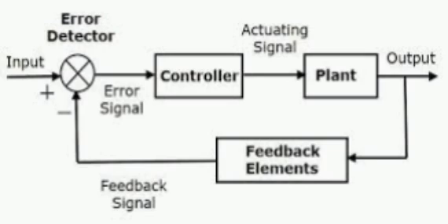Type and order of system. Every transfer function represented in the control system has a certain type and order. The steady state analysis depends on the type of the system. The type of the system is obtained from the open loop transfer function, that is G of s into H of s. The number of open loop poles occurring at the origin determines the type of the system, that is G of s H of s equals k into 1 plus s t a by s power p into 1 plus s t 1. P equals 0 for type 0 system, P equals 1 for type 1 system, P equals n for type n system.